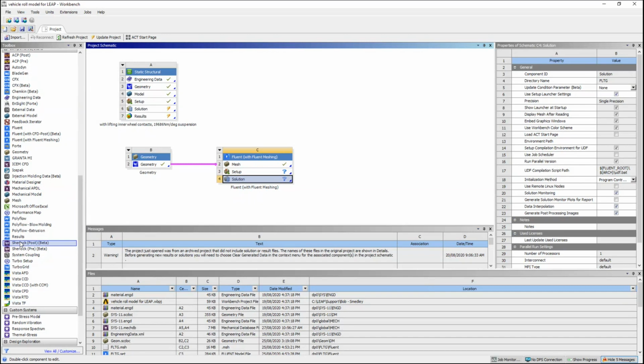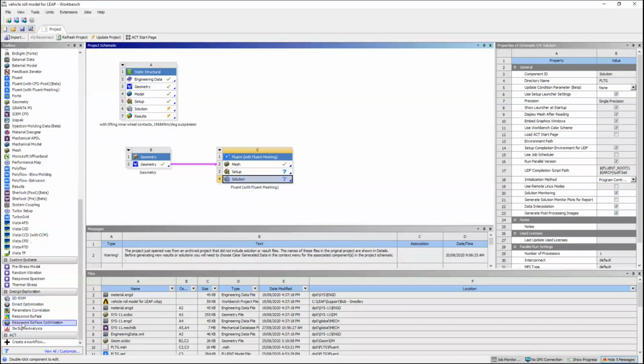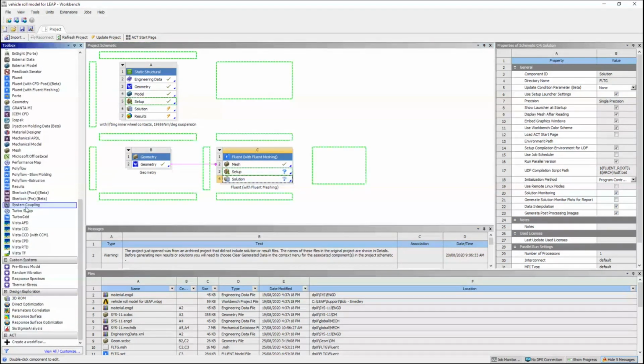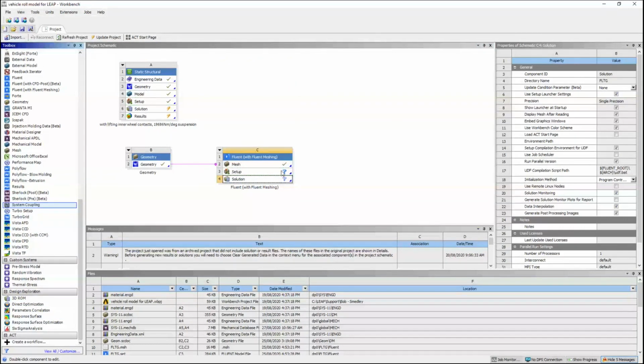And what we can do is we can link in a system coupling, right? And now we've got our static structural analysis, and we can link in our static structural and our system coupling, and that's going to transfer data between our CFD analysis to our FEA and back from our FEA to our CFD. So CFD is going to be transferring pressure values, force values, and FEA is going to be returning things like thermal expansion or stress, not stress, but deformations. Okay, great. Thank you. No worries.